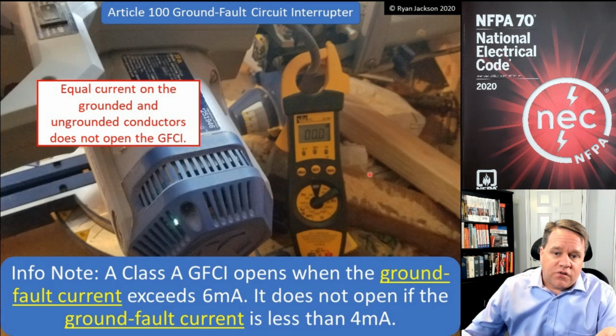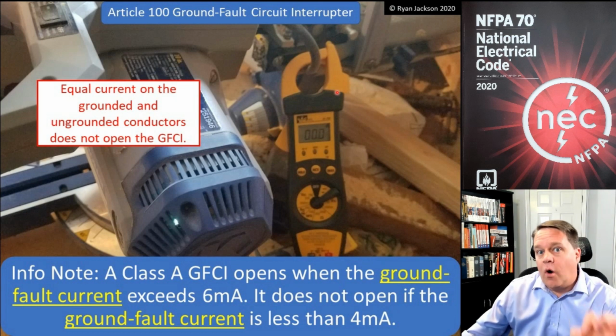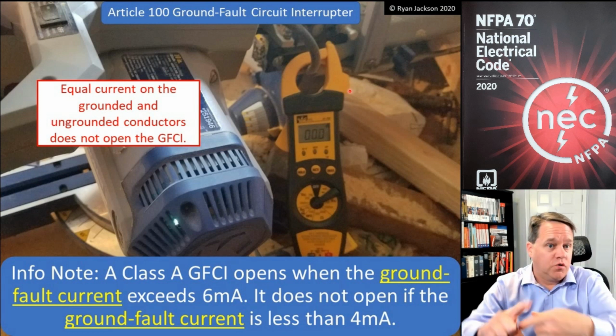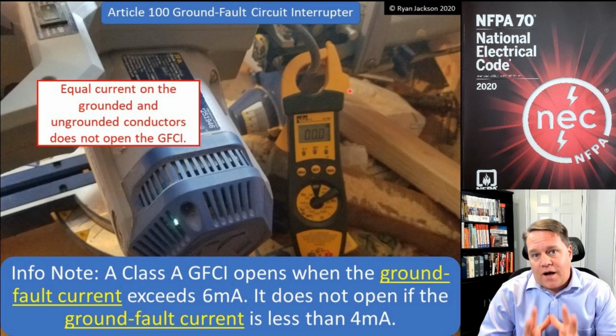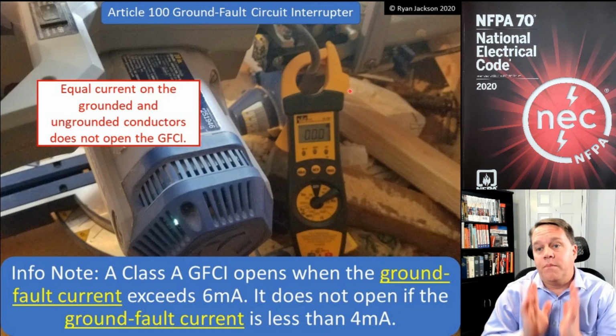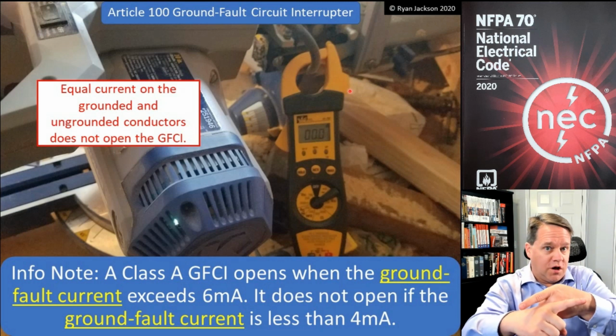So if I still had my ammeter connected, I would actually read 0.01 amps, right? Because there's more on the hot than there is on the neutral. Well, that's indicative of a problem. So a GFCI works in that exact same way. A GFCI is measuring the current on the circuit conductors, and they better equal the same thing. Current leaving must equal current returning, right?